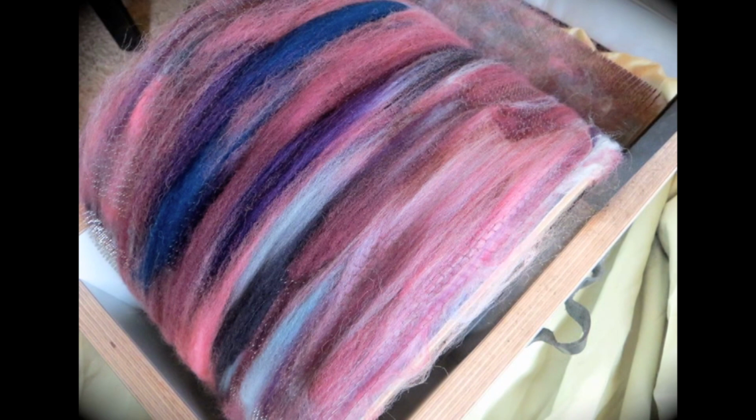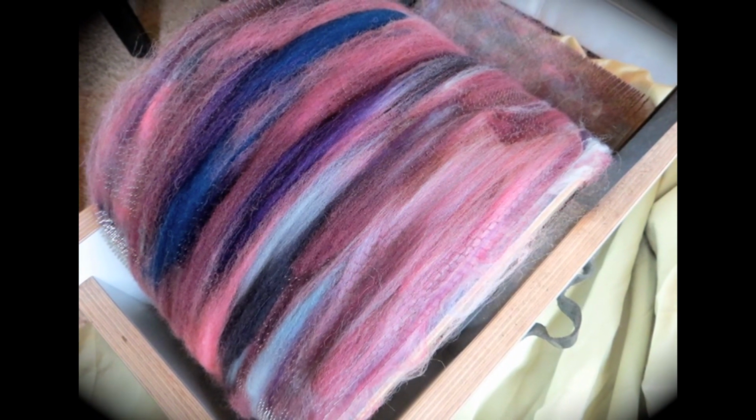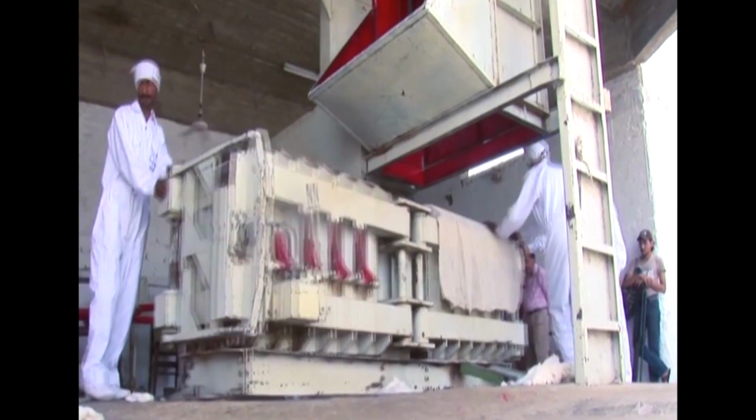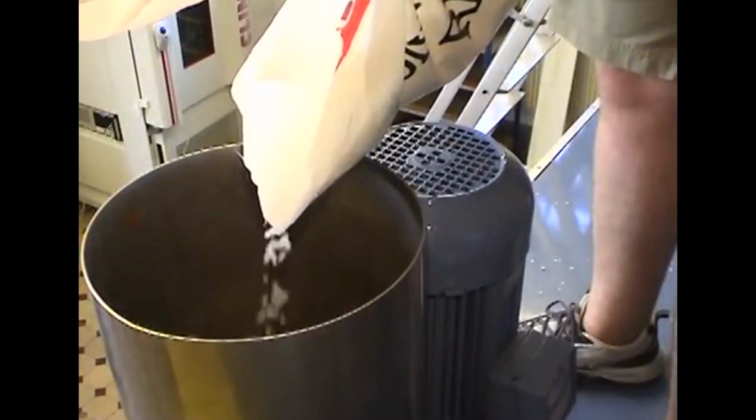Unless it is blended with some other fibers, they are all produced in a filament form only. When they are blended with other fibers, they are cut into smaller staple lengths and then blended. These manufactured fibers have different polymers. The polymers are produced and come to the chemical spinning factories in the form of chips or in the form of powder. These chips and powder should be made into a liquid, and then the liquid should be made into a linear polymer, so that it becomes a filament.